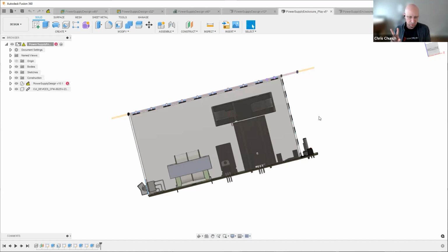There are two problems we'll have with that. One is it'll make it much more challenging to solder, and we're going to have to apply a lot more heat to the pins on that component to make sure that they solder effectively. And two, now we've got a big bulky device at what we call the plated through hole insertion. We go through a series of processes. We do SMT assembly, then the through hole devices are placed into location, and then we go on to manual soldering or wave soldering or selective soldering, depending on the volume.